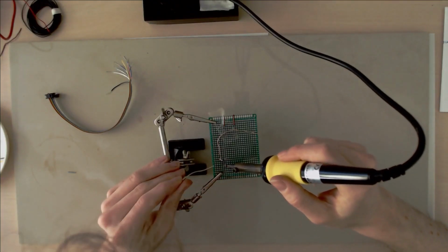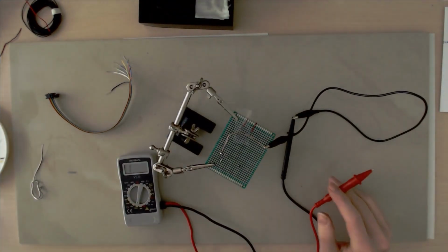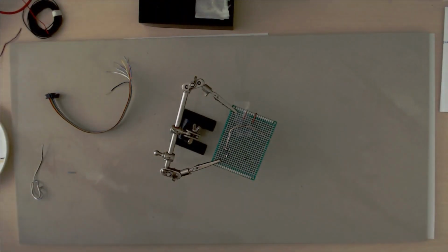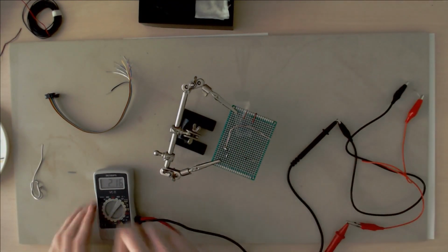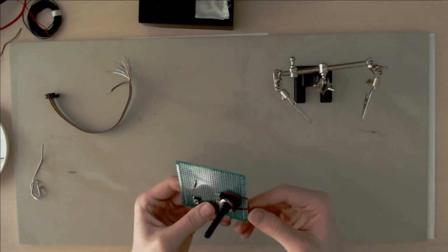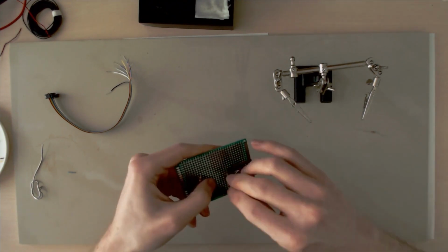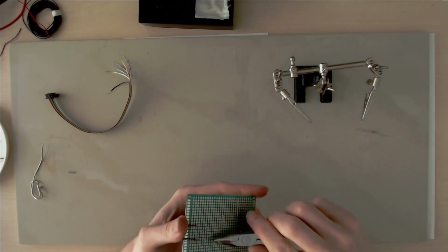The first thing I did was the preparation of the connection cable. I used a standard 10-wire ribbon cable and a pin connector having 2 rows of 5 pins each. This plug fits onto the pins of the STM Discovery board and covers all the pins the gamepad needs. While doing this, I measured continuity between the plug and the individual wires and carefully wrote down which wire color will connect to which pin.